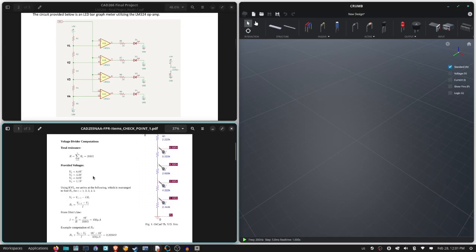And if we look at each step, we have 9 volts. Now we want 8 volts at this junction. So that means we want 9 volts minus 1 volt, so over resistor 1 has to drop 1 volt. And since we have 8 volts now here, for our second voltage we want 4.3 volts.